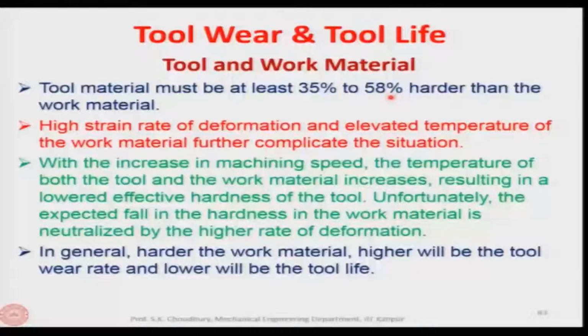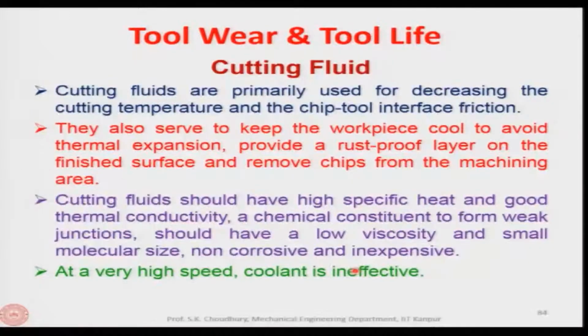So, therefore, the tool wears out more, and therefore, the 30% to 58% more hardness is required for the tool material than the workpiece material. In general, harder the work material, higher will be the tool wear rate and lower will be the tool life. This is understood. This I already said to you earlier.